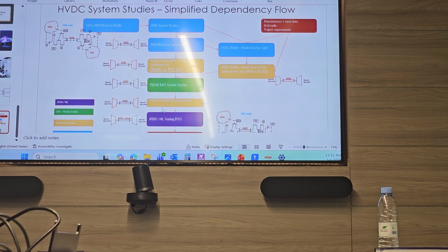So now whatever you simulate, like a short circuit, these devices will inject into your real cubicles from the manufacturer all these voltages, curves, fault simulation, and you will monitor how your cubicles will react.